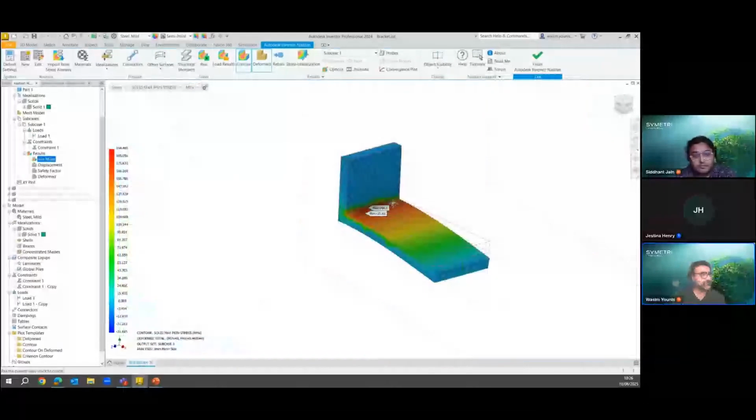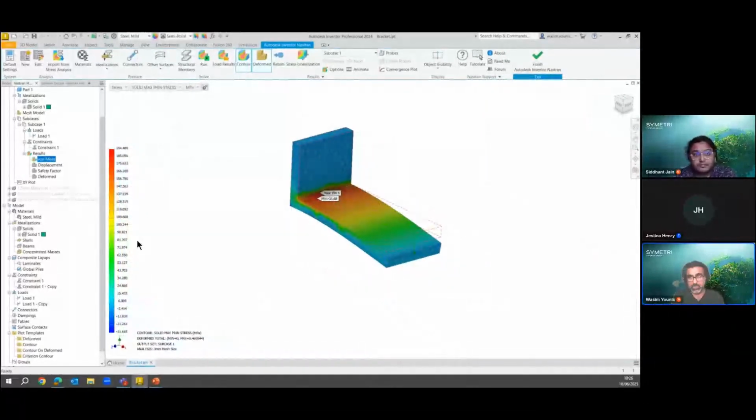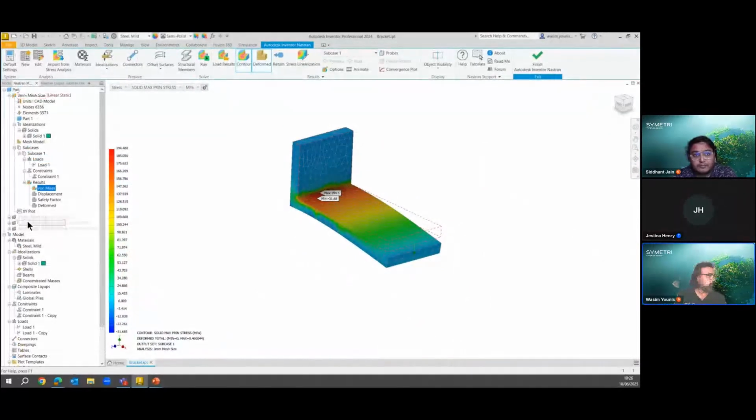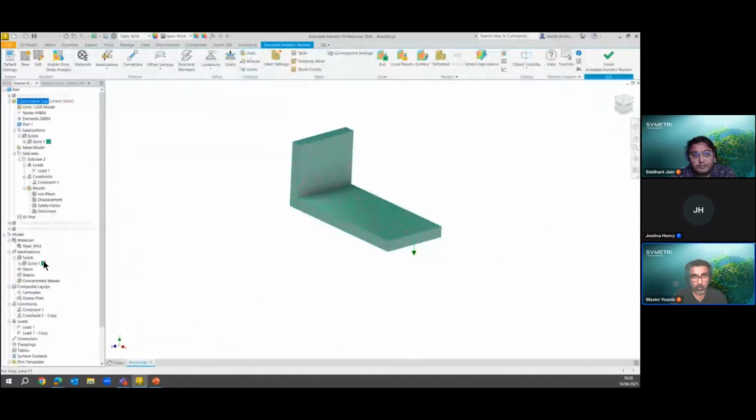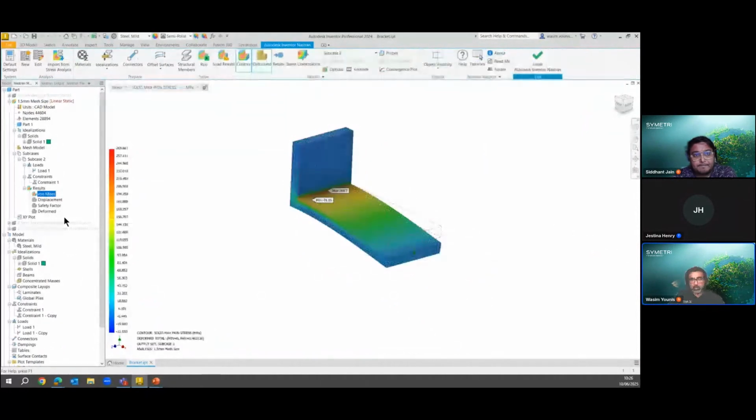So okay, that's fine. Based on my recommendation of 3 millimeter mesh size, I'm going to apply a global mesh size and say, right, let's go and have a look at the next one. I'm looking for a stress value within 10% of 194, so less than 220. If I go into here and click on display, it goes to 270. So this is where frustration happened. This is day to day, guys. Okay, so now I get 270, look at max principal. Okay, so then I hope, let's try the third one.